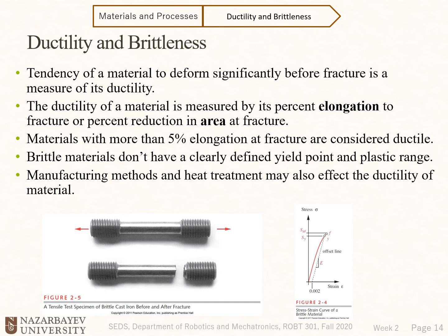Okay, so here we have a brittle material. Cast iron is a brittle material. They have high carbon, and the high carbon content will make the iron more brittle. So you see that we don't see that necking phenomenon that we used to see in steel, in more ductile materials. Yes, and that's why ductility or brittleness could be measured by percent reduction in area at fracture.